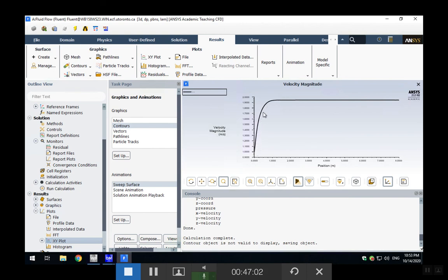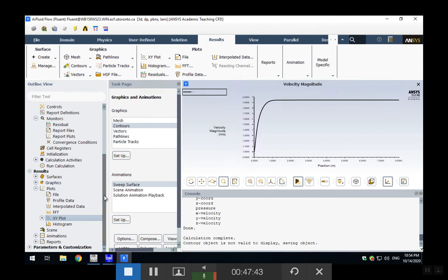the velocity at the center line changes until the flow becomes fully developed and it doesn't change anymore. And remember, for example, one question in the exam would be giving you something similar, asking you, using your simulation result, find the fully developed length. So the way you would do is you would perform the simulation, you would create a center line, then plot this, and from here approximately measure where the fully developed length is, for example, which is around 98% of the constant. So it would be around here, 0.8 meter is your fully developed. And you can have different plots.